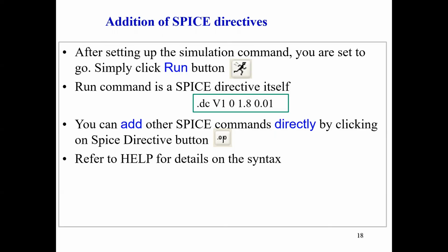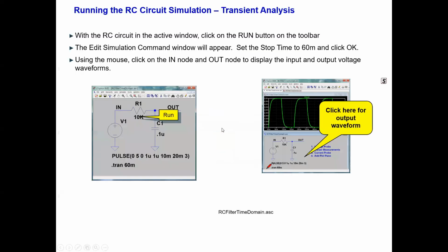If you have any problem regarding syntax, you can simply click on help, and some commands like .op can be added using the given list. So suppose you want to do this, you go for simulation and you will get this kind of curve.